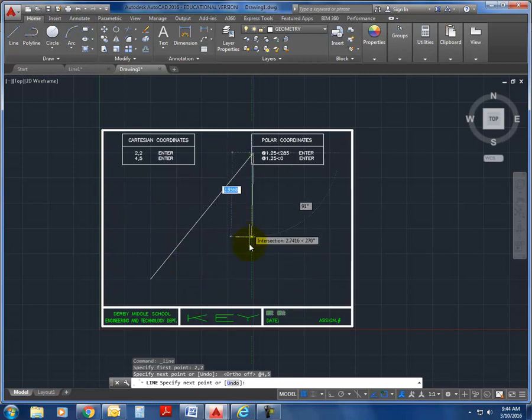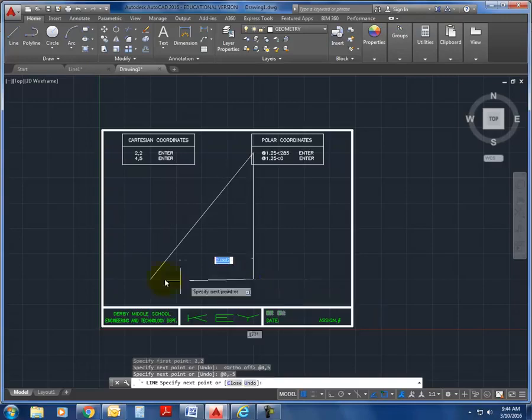Now imagine I want to create a triangle. Well, if I want to create a triangle, I want to move down and none in left to right. So let's go 5 down. So I want to type in 0, comma, -5. And that brings me down, aligned with this. And then I can click over here, but I could also do -4, comma, 0 and close that. And then when I'm finished, I can just hit spacebar. Okay, so that is the way to use Cartesian coordinates.